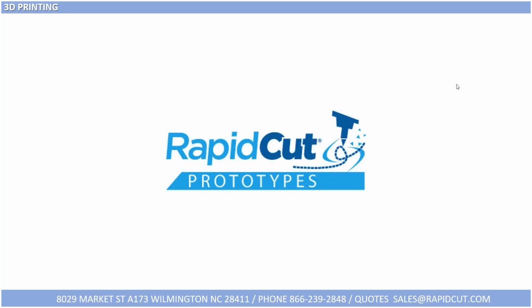All right, I've got a question here regarding direct metal laser sintering. No, this is not a process where you can expect to get a part in a day or two. I know that's very exciting when you think about CNC machining and just-in-time manufacturing. But DMLS requires a wire EDM process to remove the supports, and the supports themselves are metal. So at best, you're looking at 3 days for a lead time on that part.